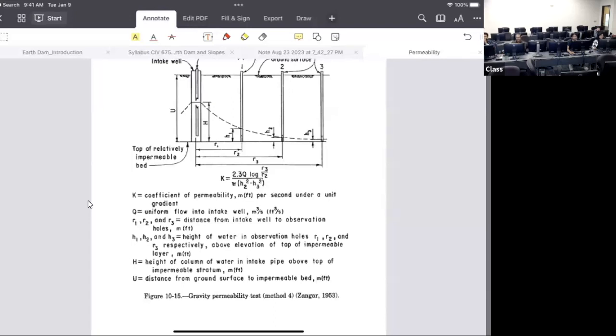Okay, think about it. So let's say you have the sand and clay, all right? So sand, highly permeable, right? You try to create a constant head. It will be possible for sand. Why? Because if you want to maintain the head constant for all time, we need a highly permeable soil. Okay, very good. You're right. Exactly. You can keep a constant head only in sand because sand allows the flow.